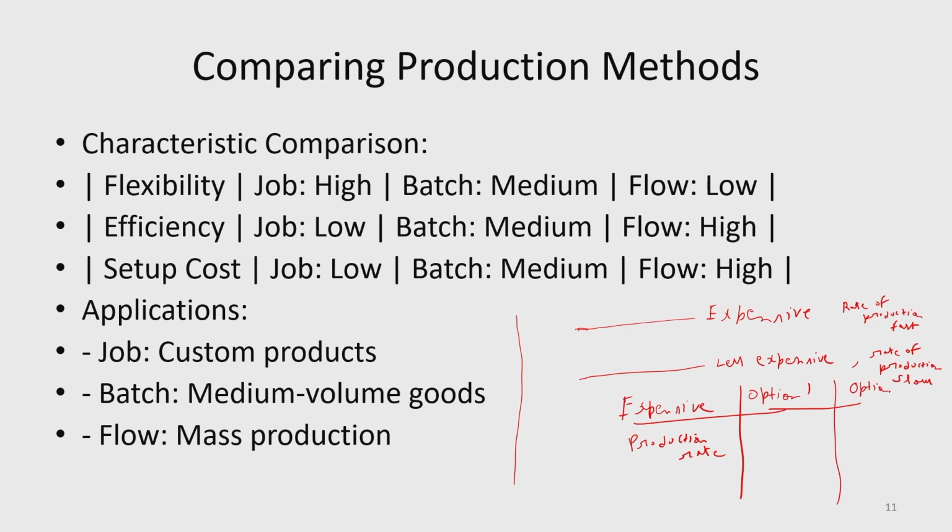In the expensive category, because option 1 is expensive, it will cost more money, so suppose you give a 0.7 rating to this. But option 2 is less expensive, so you can give 0.9. Production rate wise, because option 1's production rate is very high, so very much desirable, you can give 0.9 here. And in option 2 production is slow, so you give 0.6. Now you want both the objectives to be satisfied, you may make a suitable criterion, like you can say the overall performance index is the minimum of the membership grades.